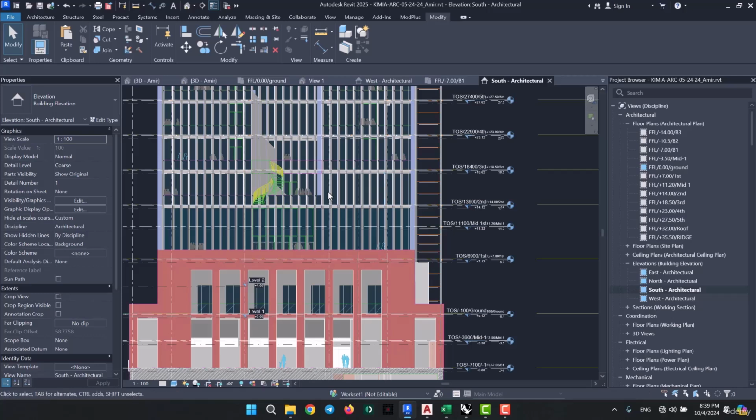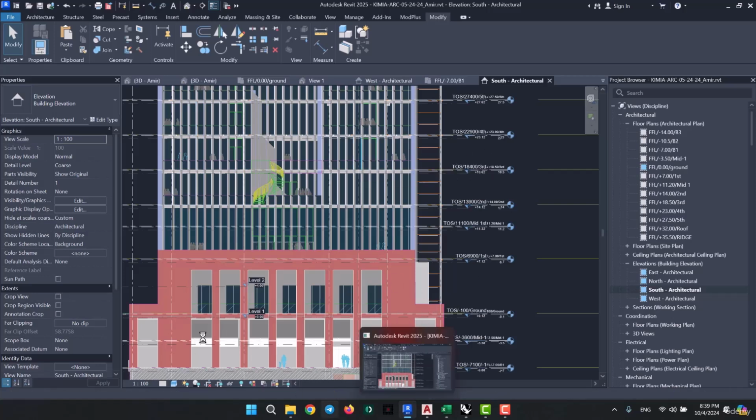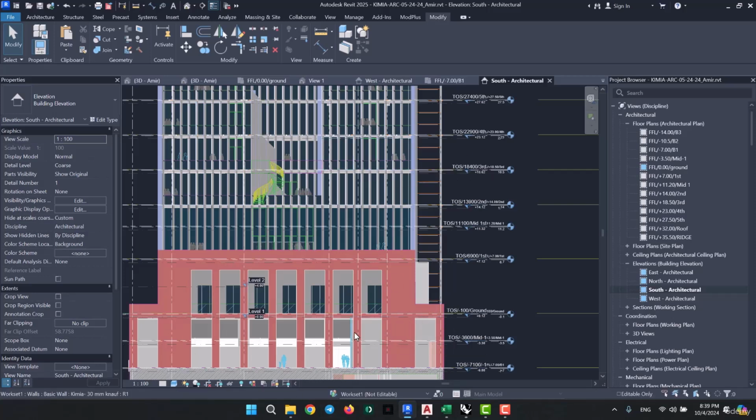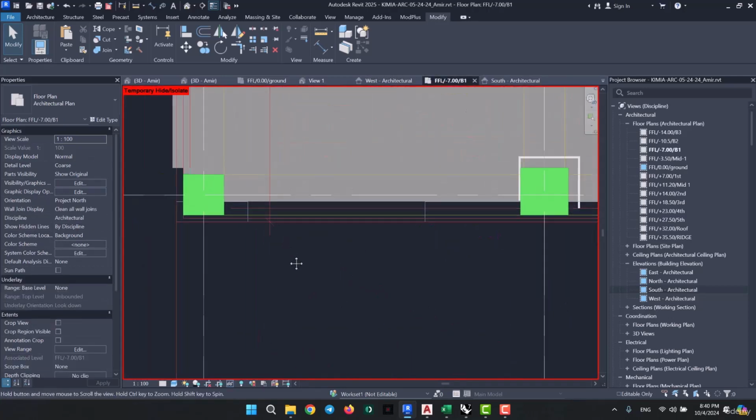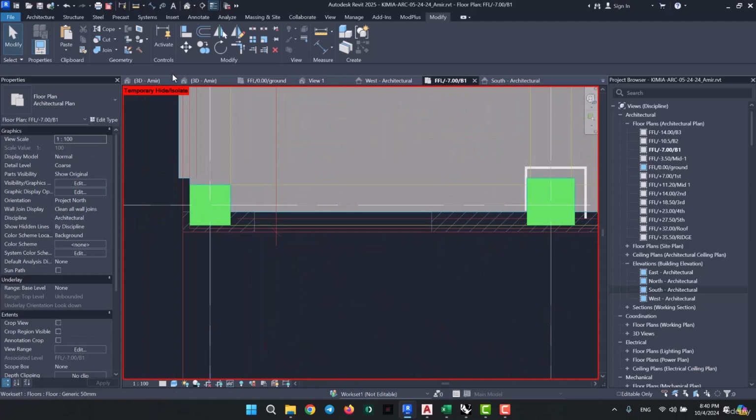Alright, so we said that we're not going to be focusing on the upper parts, and we're going to be modeling this lower part instead. So basically, I'm going to have to go over to the first basement and draw a wall, then use the Edit Profile tool to take these rectangles out of it. So I'm going to go to the first basement plan, where we can also see that our AutoCAD plan lies.